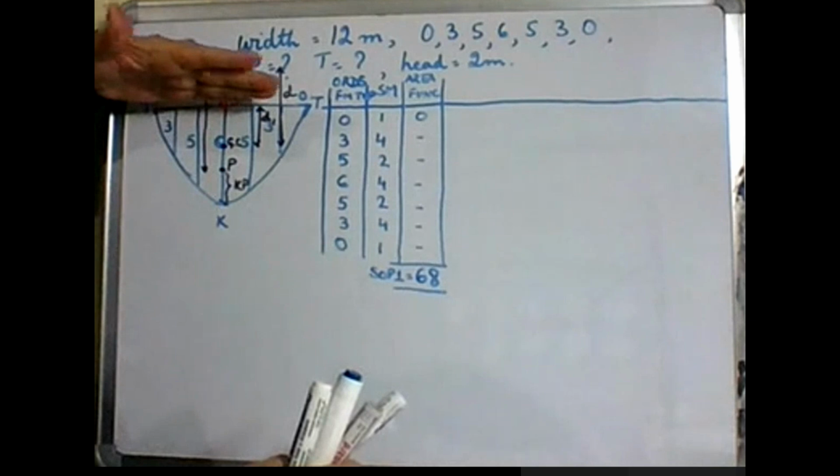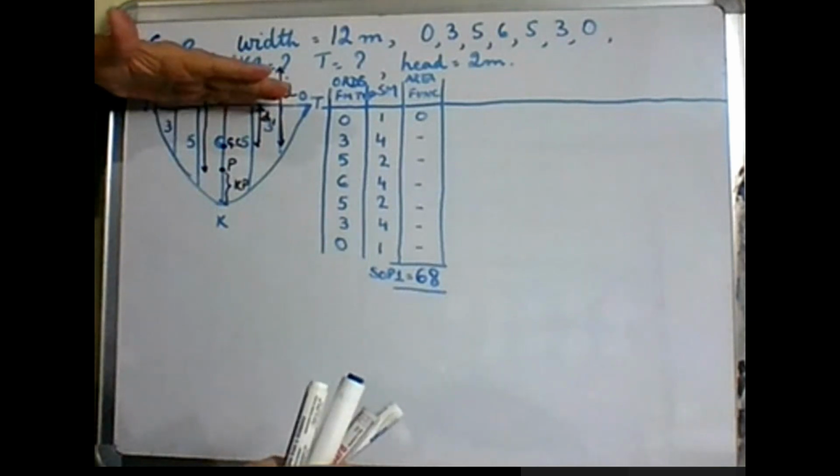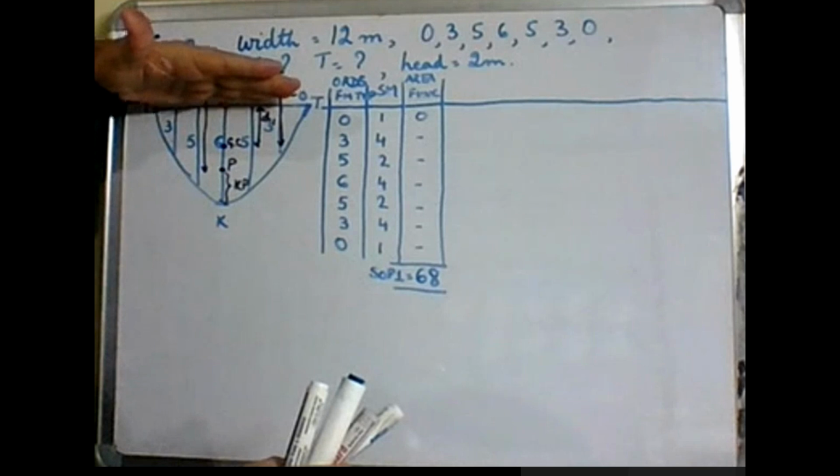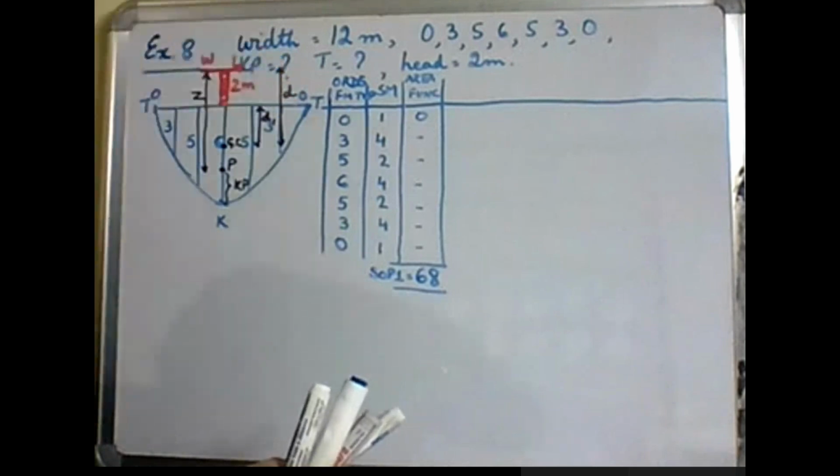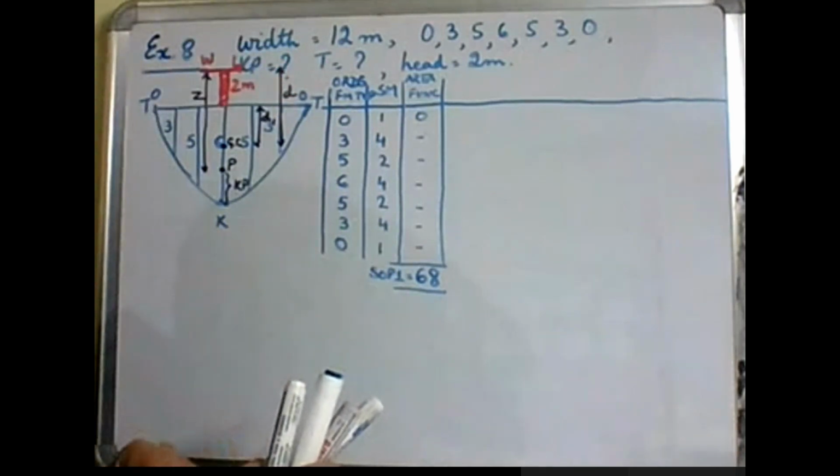It is measured from top. So if I put my hand on top and check the orientation of the ordinates with respect to my hand, how do I find them? Perpendicular. So that means this question I have to do using vertical ordinates because they are perpendicular.